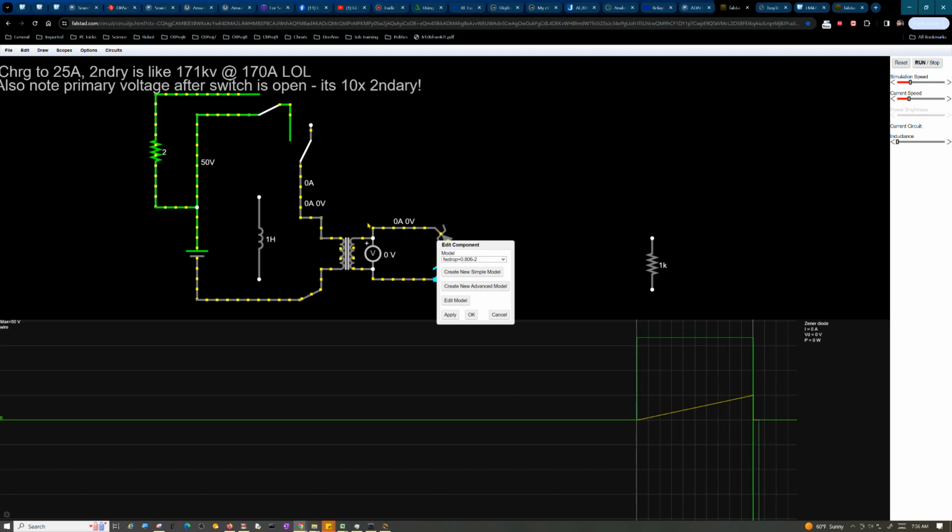Because in theory, any transformer will do this, no matter what its size. You just got to be careful what you put in the primary, because you are dealing with DC, and you can actually really easily saturate your core putting DC through one of these transformers, apparently. So, from what I hear, it's something to be cautious of. Just be cautious. You don't want to.